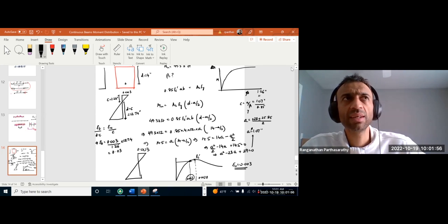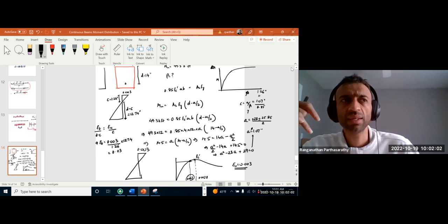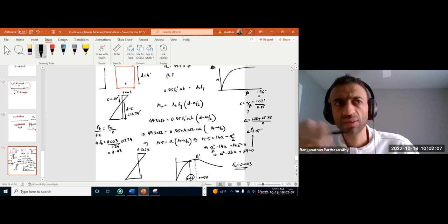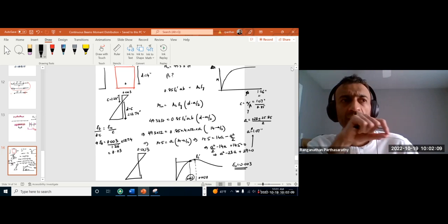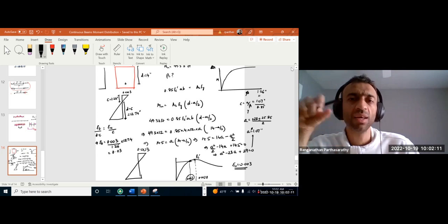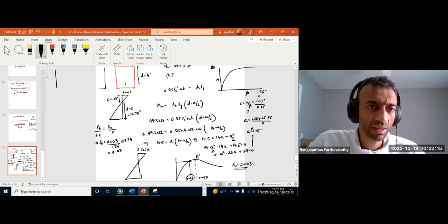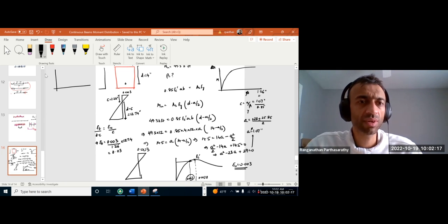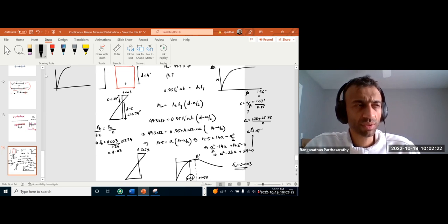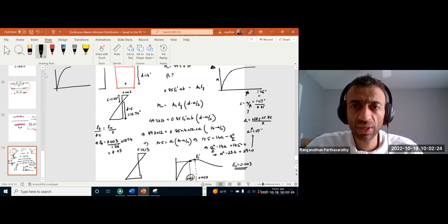So what we did at that time is purely analysis with respect to strength. We are only looking at the strength of the section versus curvature. We are not looking at the load being applied externally. That is for moment curvature. But for serviceability, we were looking purely at service loads. You are right.